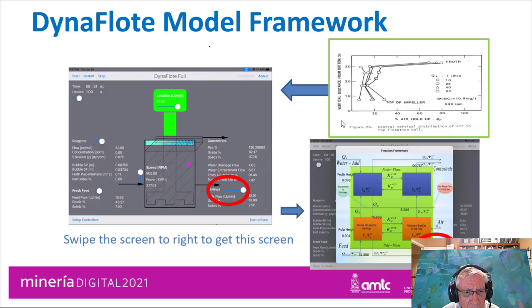This is the flotation model. The flotation model is a zero order process in which we have a tank with agitation, and we are catching the particles through the bubbles that are being generated in some form, and then these are moved up into a column. In the column we have to know the air hold-up at the bottom and then at the top, and we are managing the air so that it provides the best recovery possible at all times by doing that in real time.